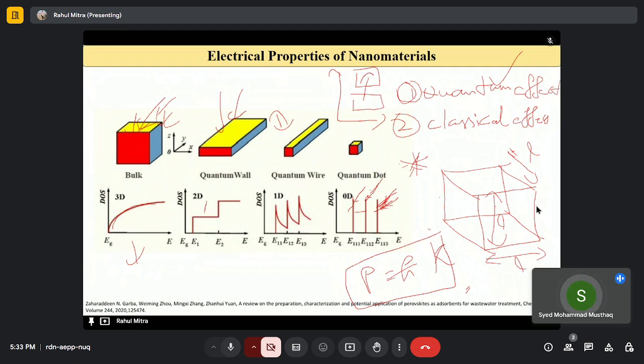These two-dimensional and three-dimensional materials are used in external circuits as electrodes. For 2D and 3D nanomaterials, ohmic contacts are possible. However, for zero-dimensional and one-dimensional nanomaterials, the contact resistance between the nanomaterials and the connecting plates is usually high. Thus, one mechanism of providing conduction is through electron tunneling.